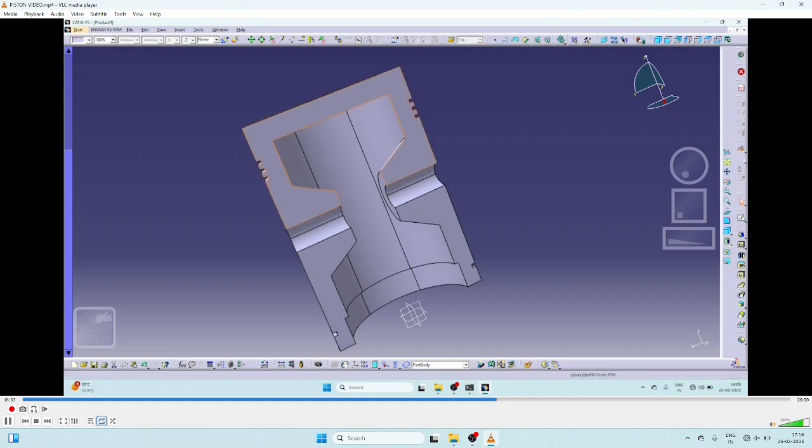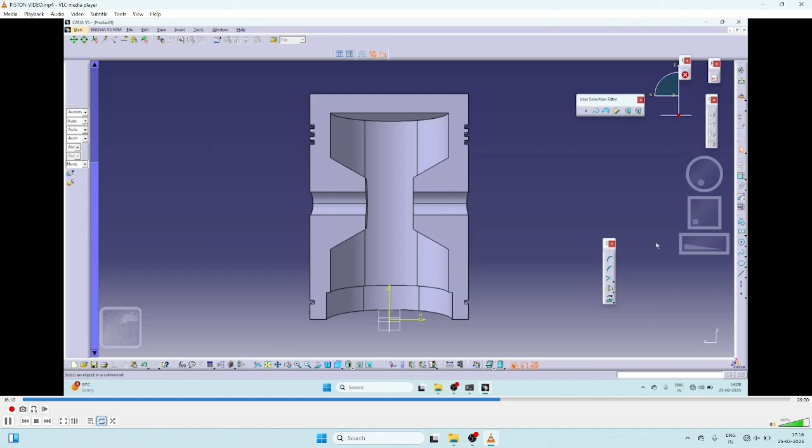So you select the surface, sketch, rectangle, center rectangle. You have to correct the positions. So from the axis, our reference is on the axis origin. Then from that, height equal to 164 on the surface of the hole.